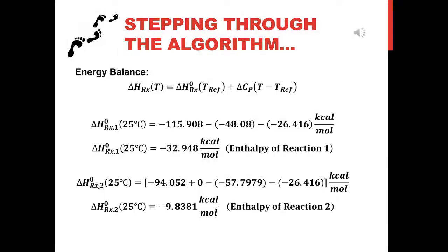Continuing with the algorithm, we next consider energy balances. Our system is designed so that the reaction is carried out in an adiabatic packed bed reactor, for which case Q equals 0 and there's no heat flow into or out of our system. We're also neglecting shaft work. In the enthalpy analysis for this reaction system, we're neglecting any enthalpy changes that result from mixing.